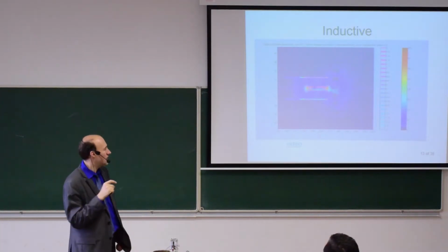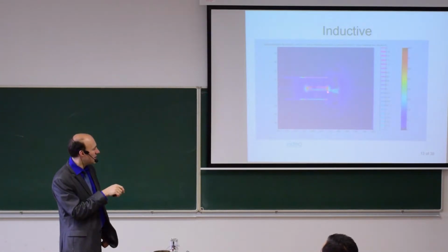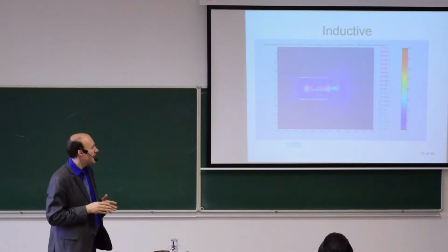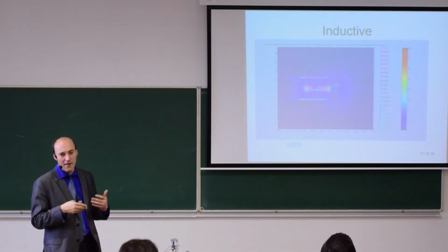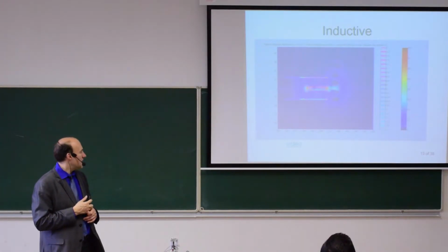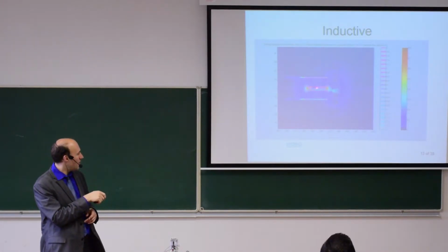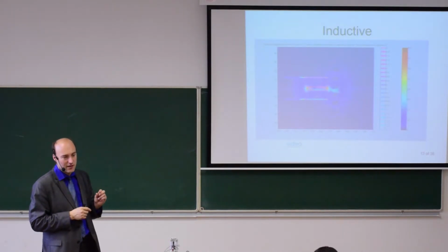So it's important to set the correct ratio between the teeth size and the sensor size. If you use a too large sensor with a large diameter, it will make a sort of average of the magnetic flux, and the signal will be very weak, and you will not be able to measure it. So this is one example where the diameter of the sensor is roughly 3 times larger than the teeth size. It works quite well.